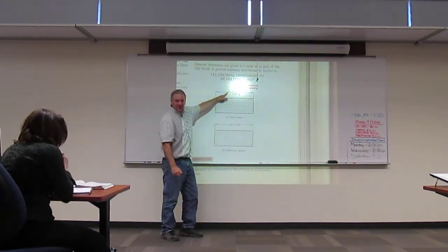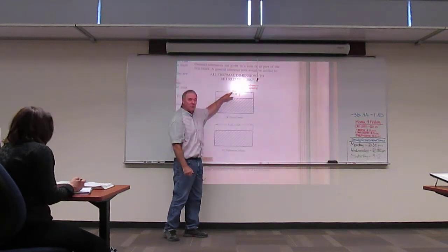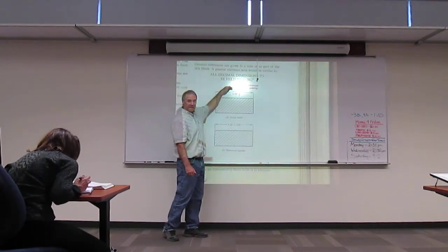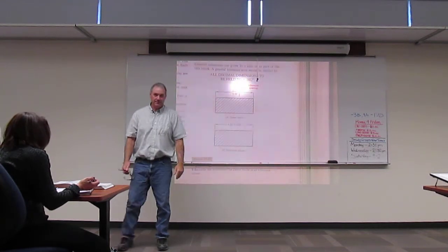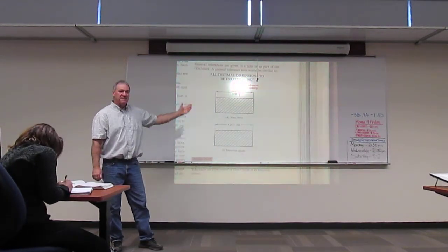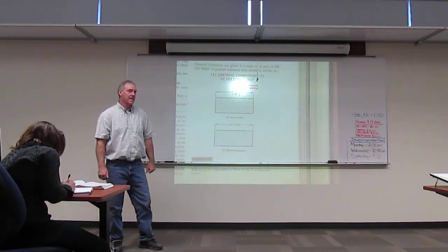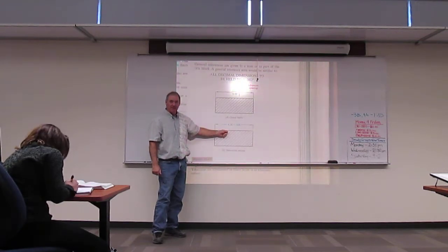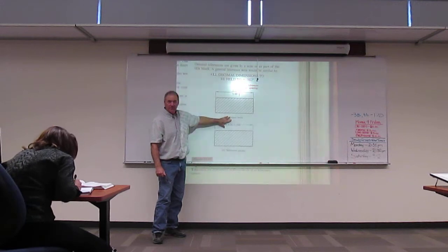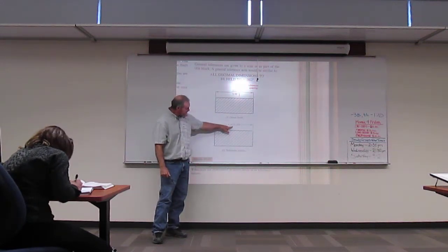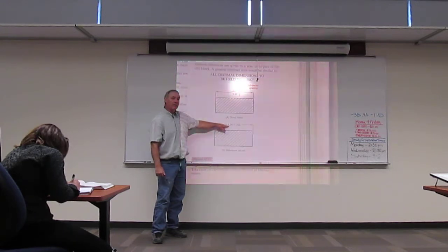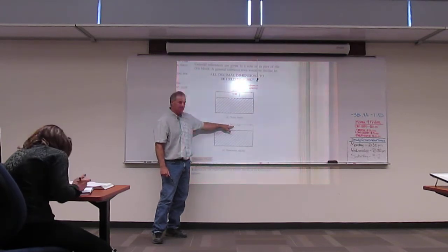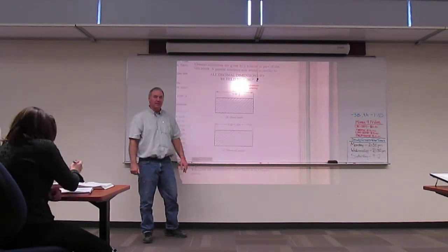This one's called limit dimensioning. Notice here there is no one size. We give the upper limit and the lower limit. The upper limit is always on top, lower limit is on the bottom. In essence, they've got a zone they need to hit. This is a direct tolerance. You also see another direct tolerancing down here. This is called bilateral tolerancing, where we're saying the basic size, this is what I want. If I can, I want it at 4. But I know you can't get there, so I'm going to say plus or minus 0.003.